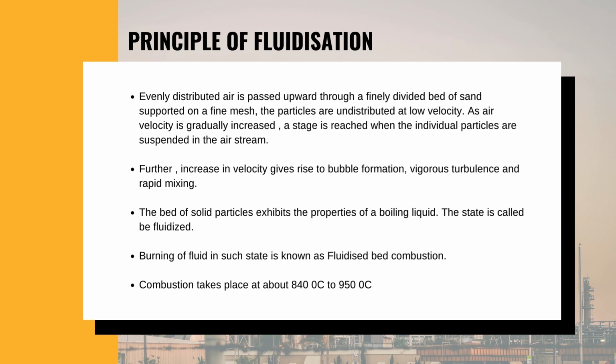With further increase in air velocity, there is bubble formation, vigorous turbulence, rapid mixing and formation of a dense bed surface. The bed of solid particles exhibits the properties of a boiling liquid and assumes the appearance of a fluid: a bubbling fluidized bed. At higher velocities, bubbles disappear and particles are blown out of the bed. Therefore, some amounts of particles have to be recirculated to maintain a stable system: a circulating fluidized bed. The principle is shown in the figure.